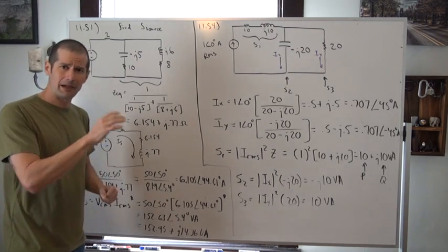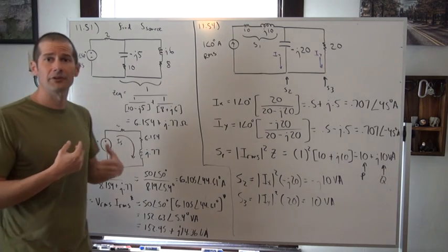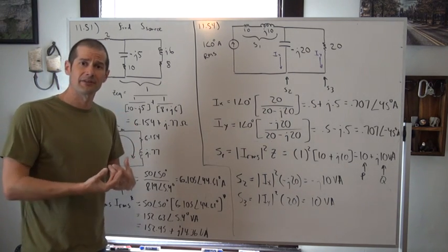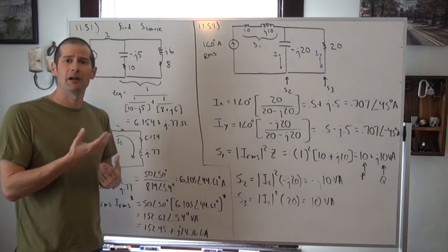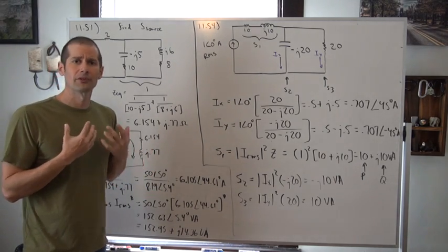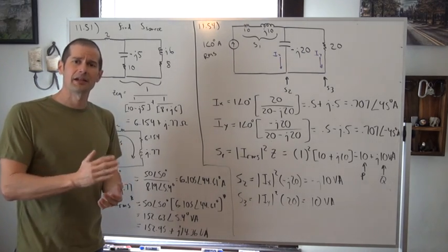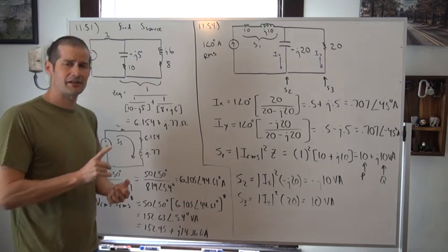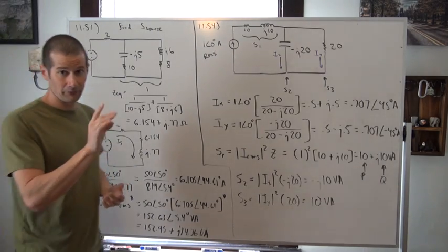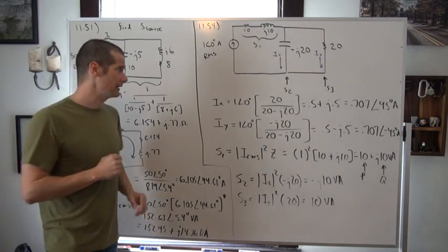And we're going to talk about power factor and what that means. Power factor is nothing more than talking about the efficiency of the system. And when theta V minus theta I become very, very close, that means it's acting more resistive in nature because the current and the voltage phase angles for a resistor are the exact same. And that means that we're getting all real power within that resistor. But more on that in just a bit.